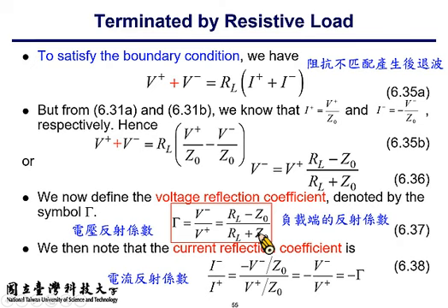It tells us that all the incident power, all the incident signal, is absorbed by the termination, providing that you have a so-called matched termination, that is, RL equals Z sub 0. If there is no difference between your load resistance and your characteristic impedance, then all the energy goes into the load and nothing comes back. The reflection coefficient is 0, and things become much easier.